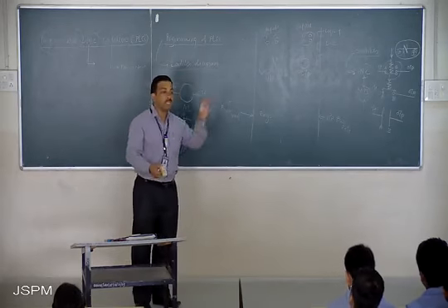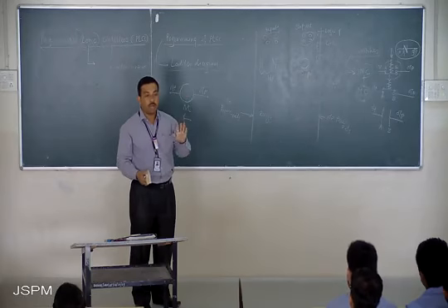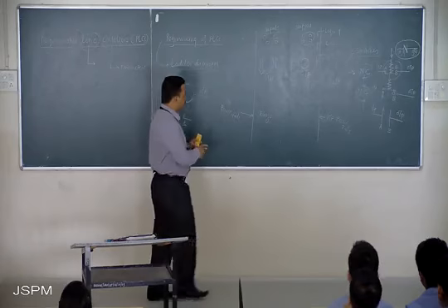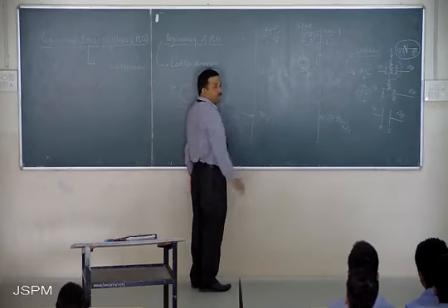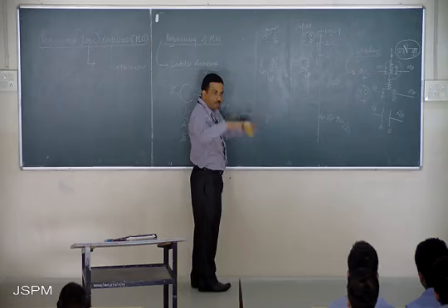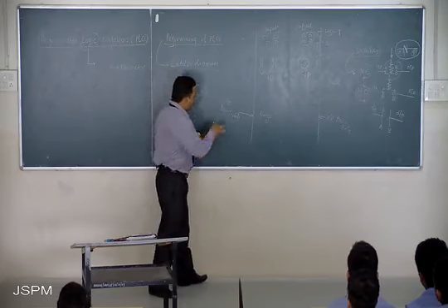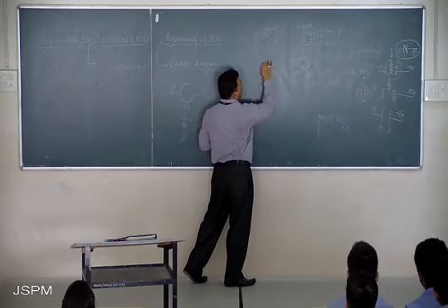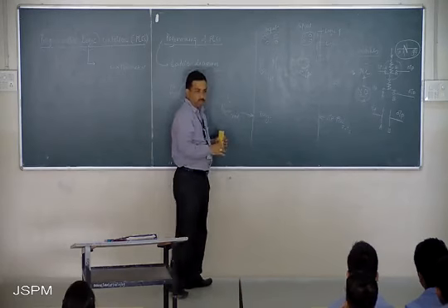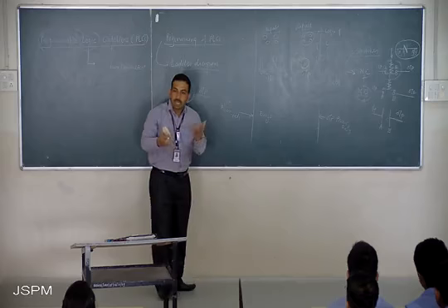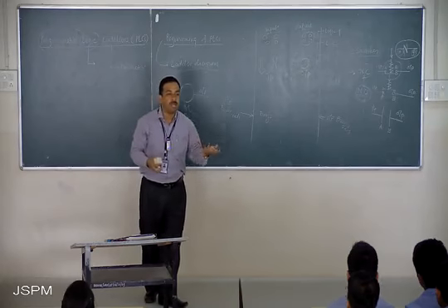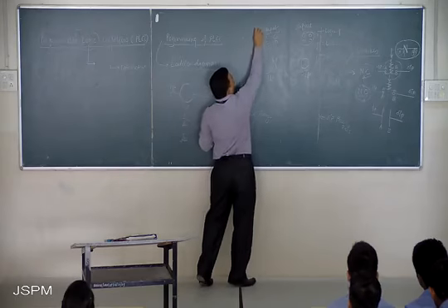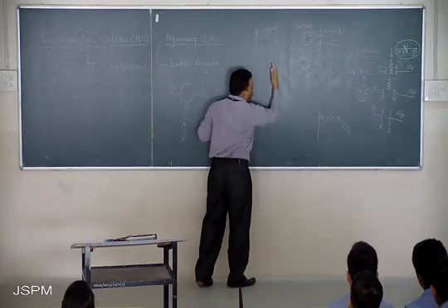There may be a question: explain the different components of the ladder diagram, or explain the ladder diagram with the help of a suitable example, right? So what you can do is explain that the ladder diagram consists of two vertical lines which are called power rails. Now this is called the input power rail, because on this side all the inputs are connected. The energy which is required to stimulate the input components will be given by this particular line. You can call this a common power supply to all the inputs.